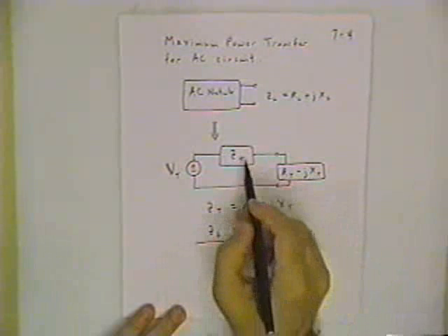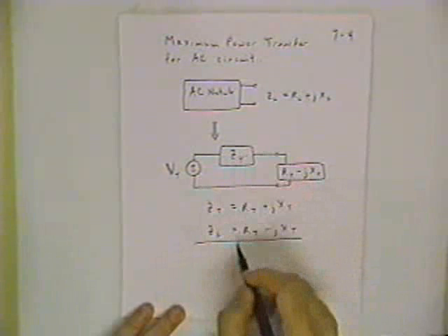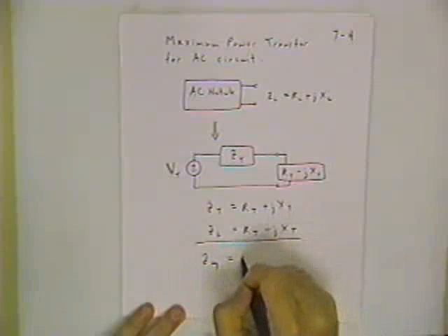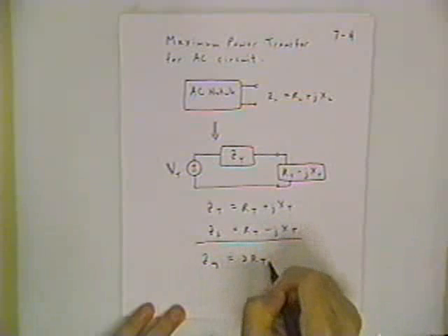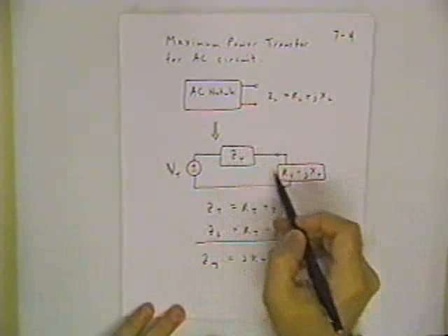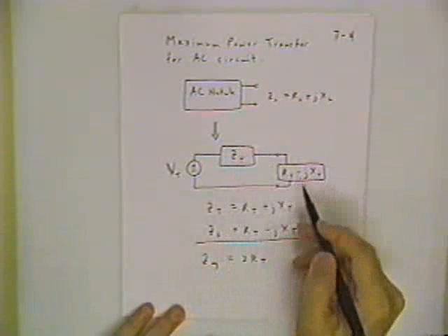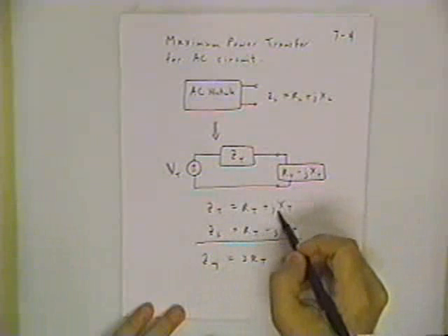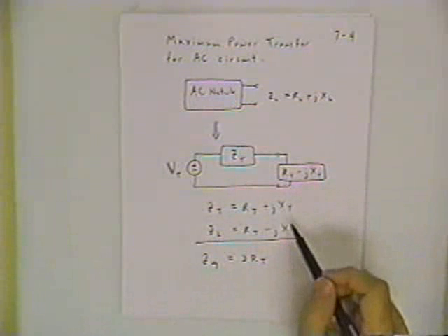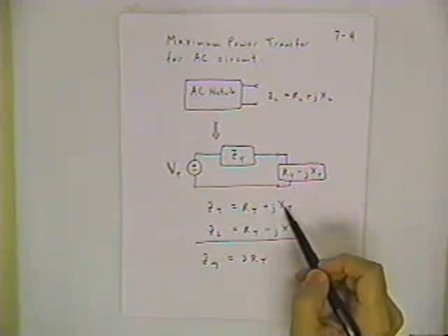And you notice what happens. These series connected impedances add together, Z equivalent gives you just a pure resistive load, if you include the Thevenin impedance and the load impedance together. The imaginary parts cancel out. And we're going to see in just a minute, the imaginary parts represent power that's trapped within the components.